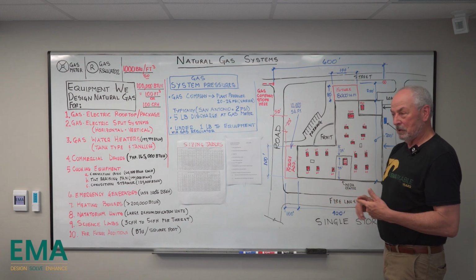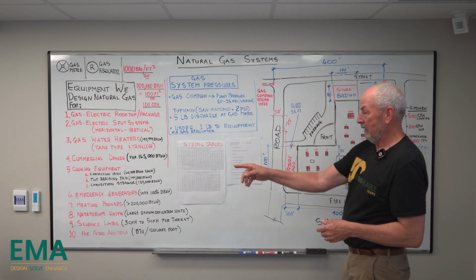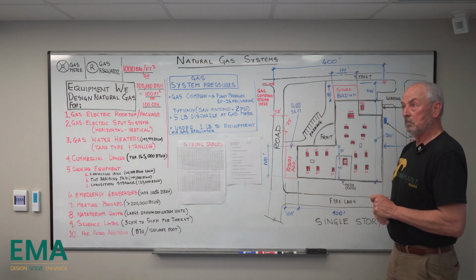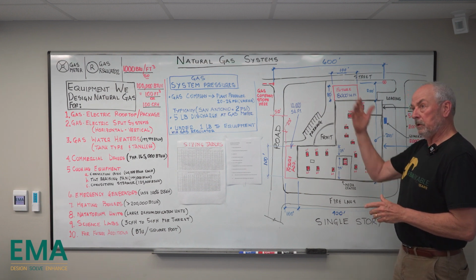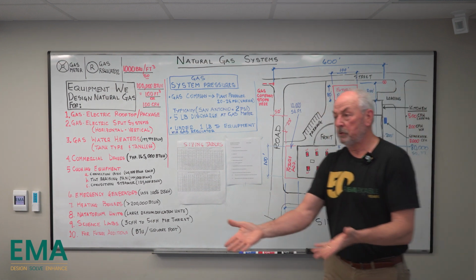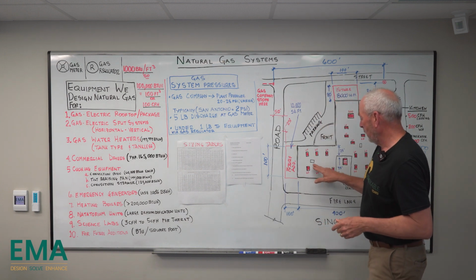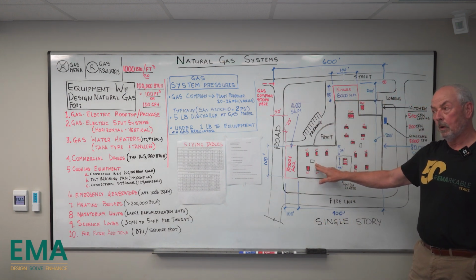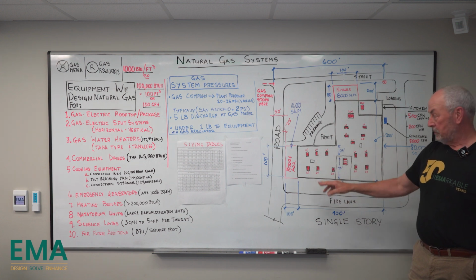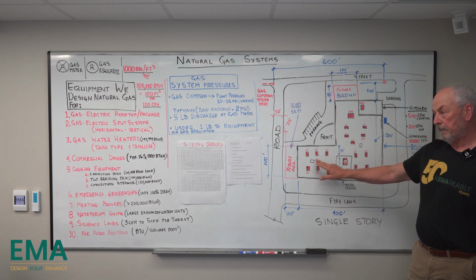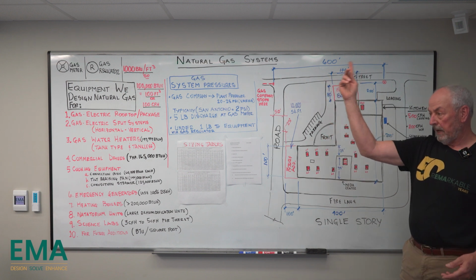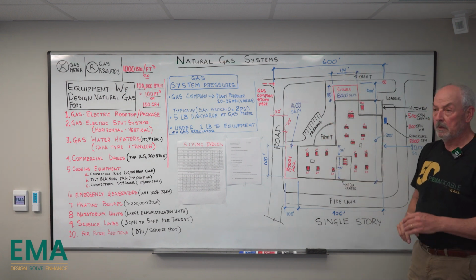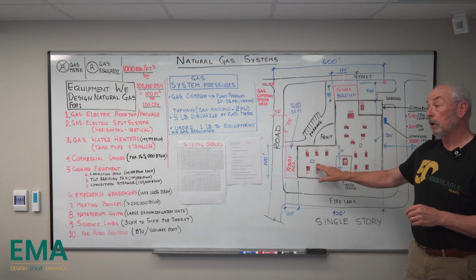So if the sensible set point's satisfied, and the unit cuts off, that room's still producing heat. So we're not trying to solve a heating issue. We're trying to make sure it stays cool so it's not damaged. So we don't specify. It's either going to be a mini split like we have in this building or a rooftop, depending on the internal load of the space.